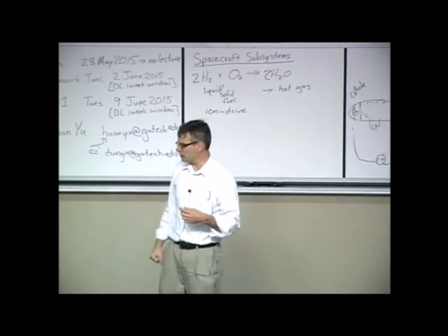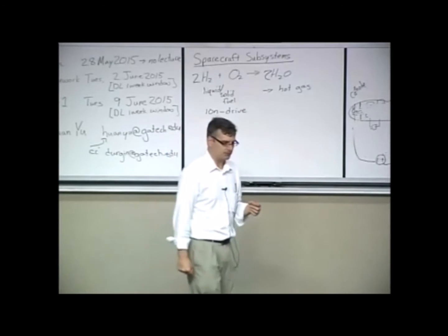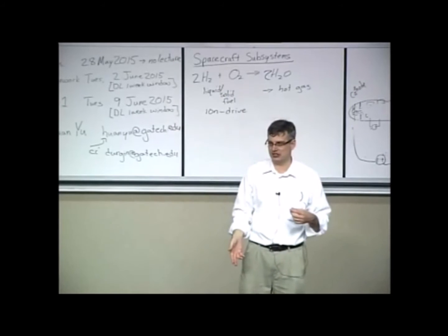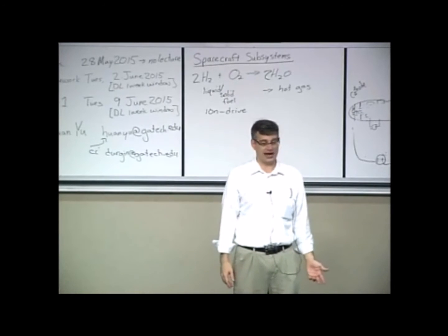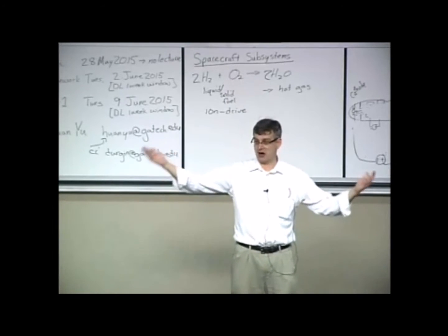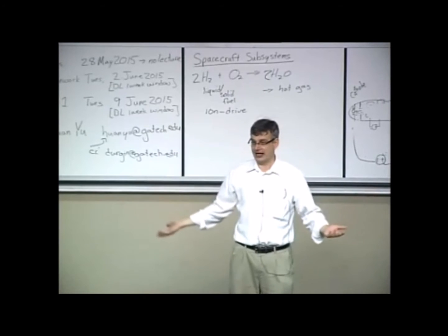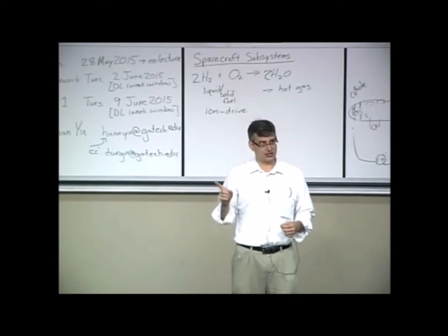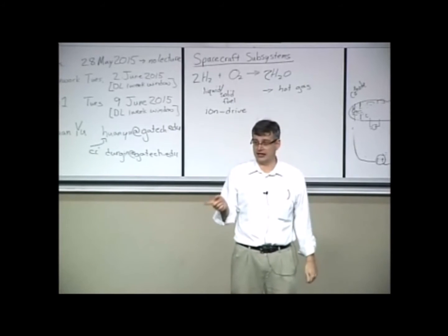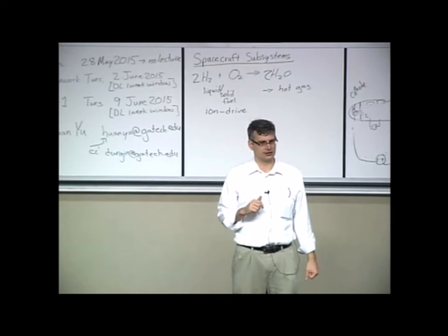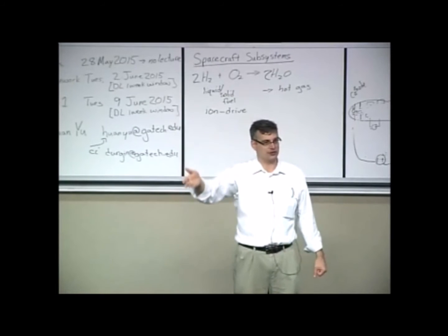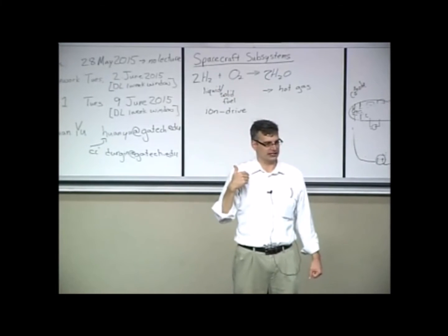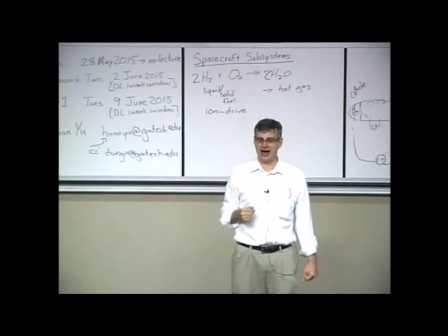So those are candidates for going to higher Earth orbit and also for deep space missions as well, because you can turn them on for a long period of time. You're going to be spending years to go into outer space and to visit, say, the outer gas giants of our solar system. And I actually think the very first space mission in the 90s that used an ion drive was a NASA mission to the asteroid belt. It was going to take several years to get there anyway. Why not turn this thing on and get there a little quicker using minimal mass?